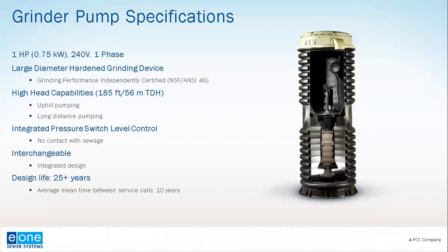We talked briefly about the pressure control design, and again, those switches are pressure switches. They're the same ones that are in your washing machine at home or your dishwasher. Very reliable, very simple, incredibly simple design, but they deliver years of reliable performance. We want them up inside that pump. They're activated by air column. And the benefit of that design is that it is actually interfacing with water level while never coming in direct contact with it.